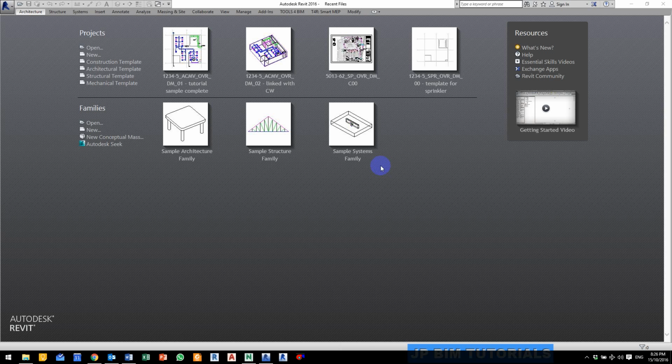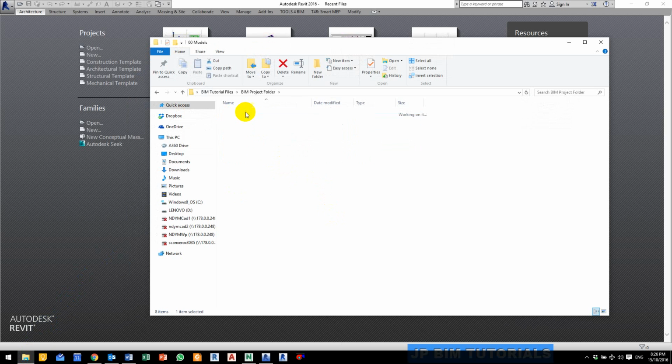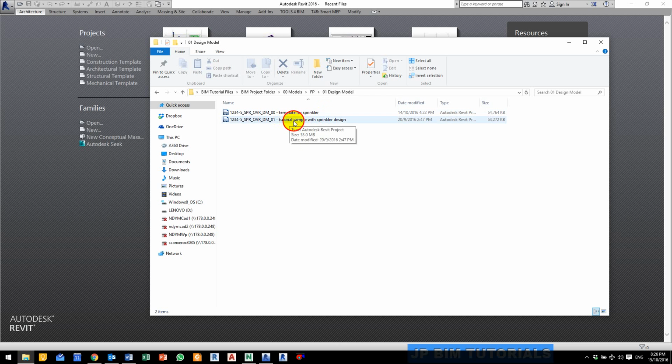In this video, you're going to learn how to model sprinklers using Smart Sprinkler. So to begin, go to our BIM tutorial files, go into the BIM project folder, models, fire, design model, and open a file with the words tutorial sample with sprinkler design.